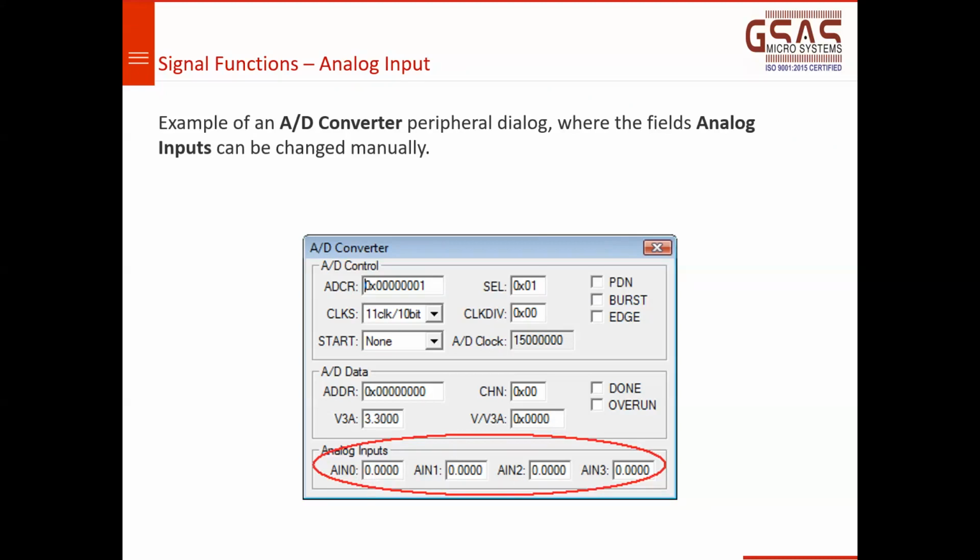ADC is configured such that it will receive the analog input and give you the digital output. That particular thing I have already written in my C program. The only thing is, how do you simulate ADC? We need an analog input, right? Because there is no hardware, you give the input through virtual registers. And these features make the Keil simulator unique. To date, no other competitor or vendor has come up with this feature of virtual registers and simulation of peripherals.